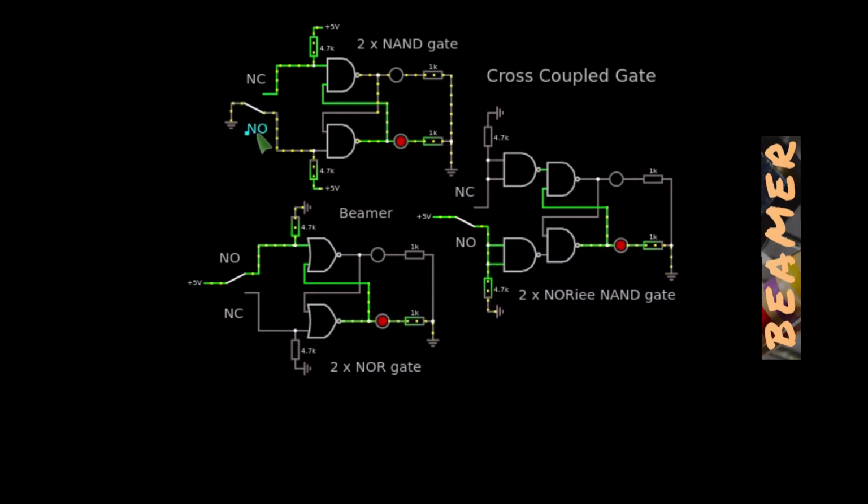And you've got normally open contact here, normally closed contact here. And I'll just go through this one in finer detail, but the other two implementations operate in a very similar way. First of all, we have the contact placed in a normally open position, the wiper of which is taken down to 0 volts. You've got two pull-up resistors here to a supply. It's stated here as 5 volts, but in actual fact I think the application ran at 12 volts. But as this is a CMOS package, it's well within its voltage supply range. So you've got two pull-up resistors.